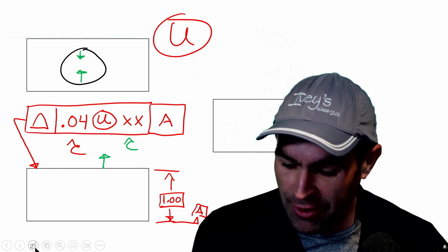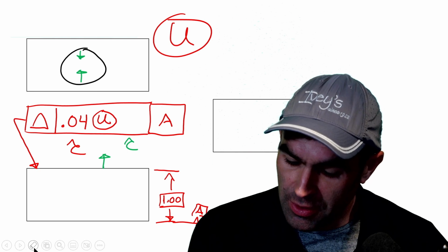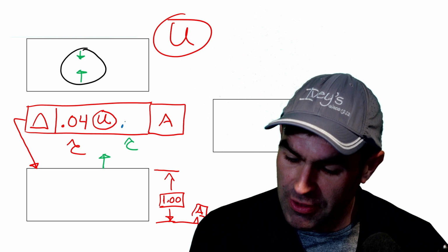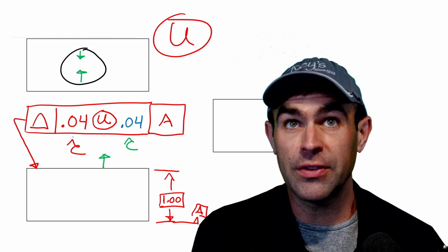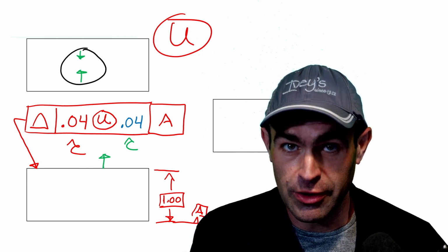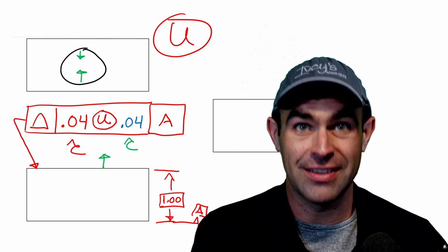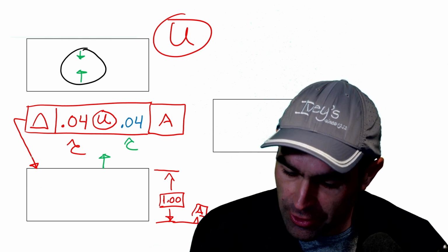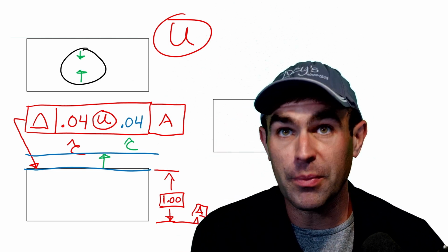So let's give it a value and try some things out. The most common value you're going to see here is a value that's equal to the total tolerance. So in this case, the way we read this, it's profile 40 thousandths unequally disposed, 40 thousandths. All 40 thousandths is in the direction that would add material. So this tolerance zone is entirely outside of the part.